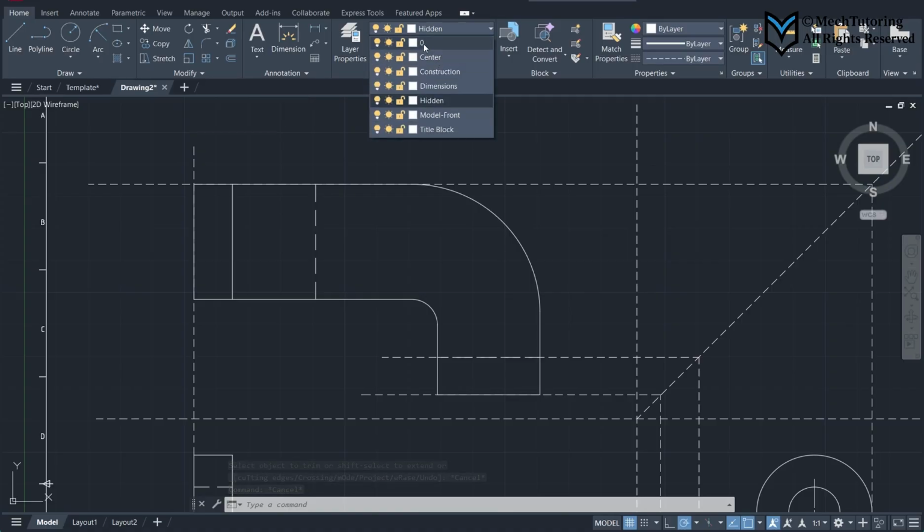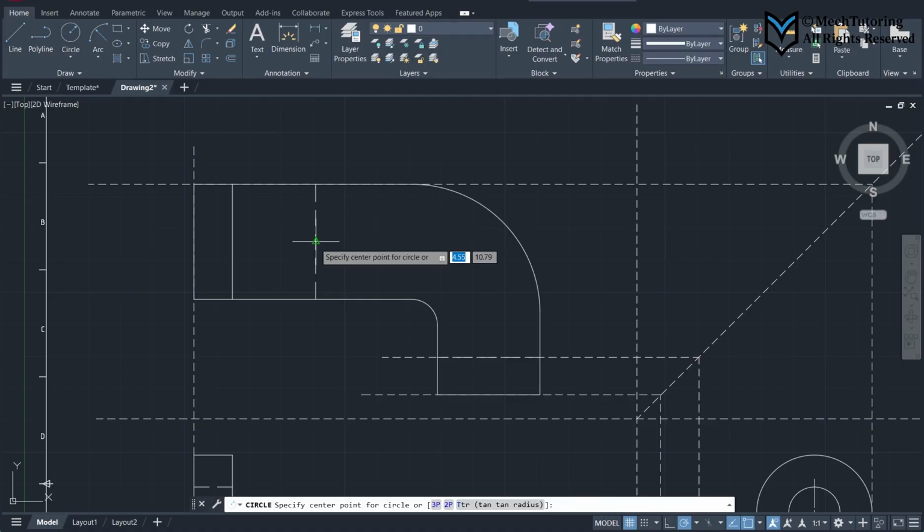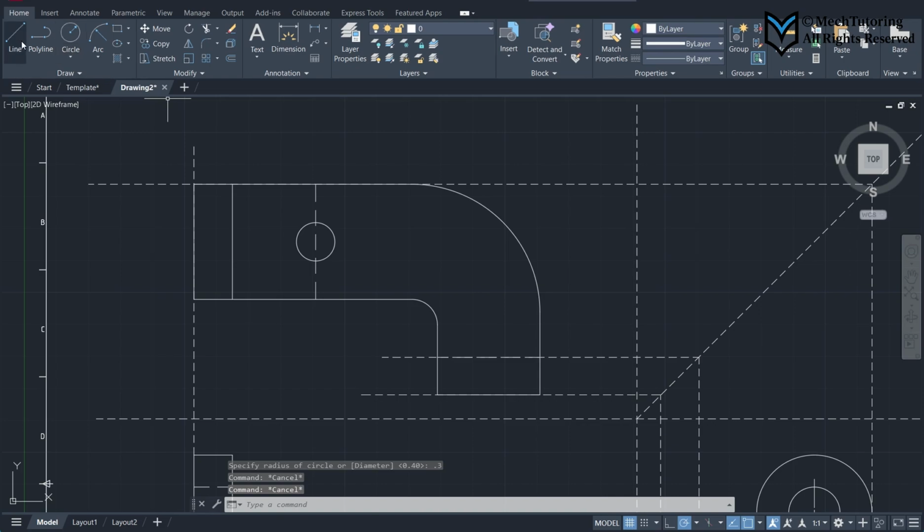So I'm gonna go main, and there's a slot here of radius 0.3. And then I'm going to draw another line from the center of 0.9 this way and copy this circle, not move, to that location and delete this line. Our slot is ready.